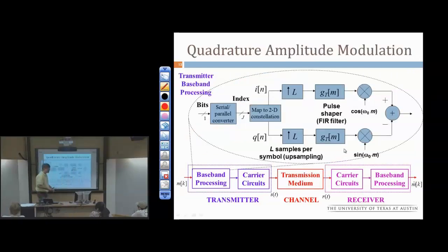So this is lab 6. This is the baseband part. This is just the expansion of that into a block diagram, right out of lecture 15 slides. So we have bits come in. We get symbols of bits. We use that symbol as an index into a lookup table. Get our in-phase and quadrature amplitudes, and then go through baseband PAM in 2 channels. So this part is baseband PAM, followed by up conversion.